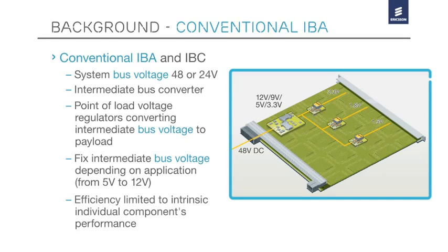In this architecture, the IBC and point-of-load performances are limited to the intrinsic performances of each module, set by design optimization during their development, resulting in unoptimized topology and unnecessary power losses when the payload is below the optimal conditions. Recent data center studies show this is true in more than 80% of cases.